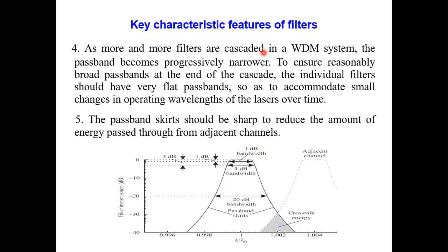My center frequency will be 1550 or 1310, and I will have multiple wavelengths. It can be dense wavelength division multiplexing or coarse wavelength division multiplexing. Every wavelength is centered around 1550 suppose, but it will have lambda 1, lambda 2, lambda 3 and so on. We cannot give the same wavelength to everyone. Every channel will have a different wavelength.